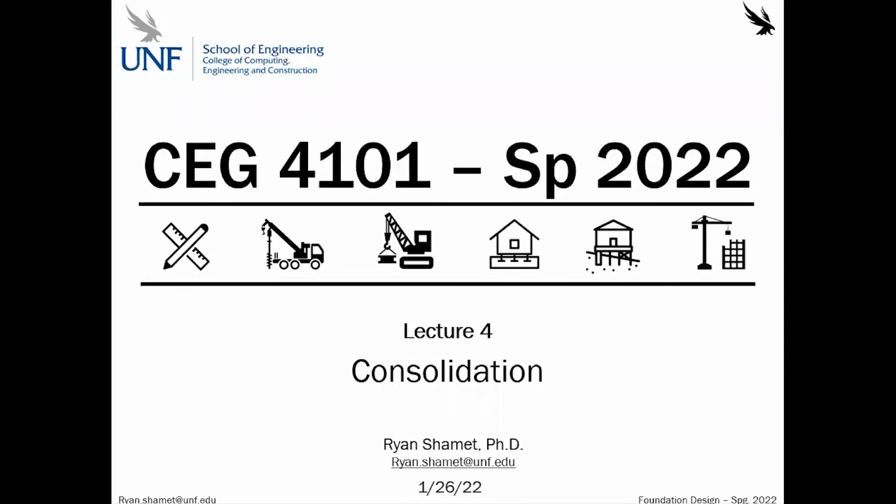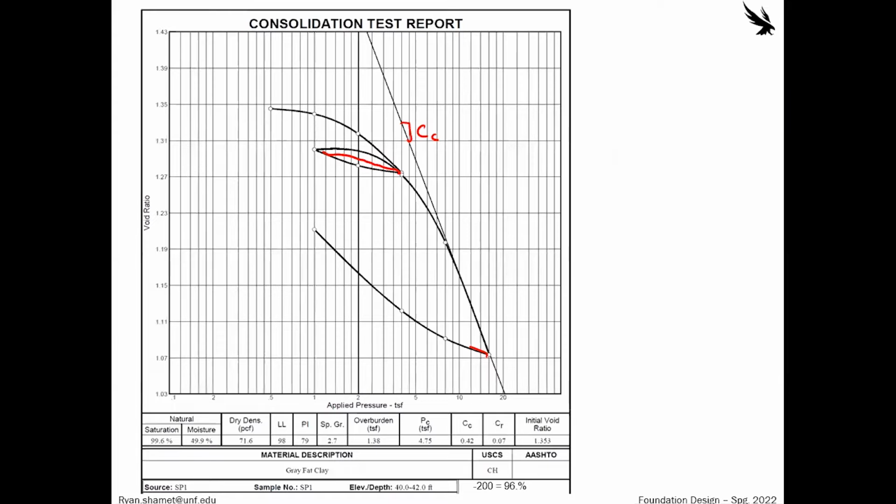Okay, so you should have noticed in the lecture notes, it'll say just reference C slides from lecture 4, because we weren't quite done with that yet. But what we ended on when we were just introducing consolidation is what an actual measurement from a real lab report looks like. And we see even though we conceptualize it as two vertical lines, we have to remember that the actual raw data is not producing a straight vertical line. So there's always assumptions and always a lot of room for error when we're talking about the consolidation test.